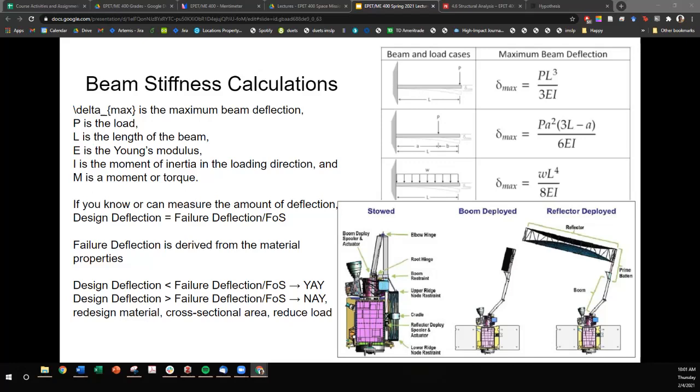You'll see here that load and deflection are linearly correlated with each other, which is why you can do this swap or replacement. It's exactly linearly correlated, so load and stress are going to have the same ratio as deflection.